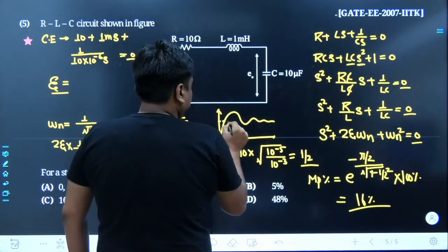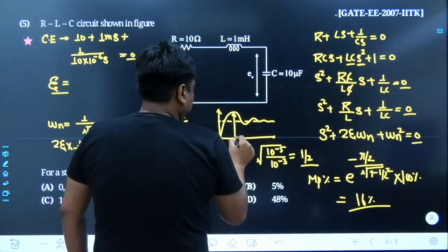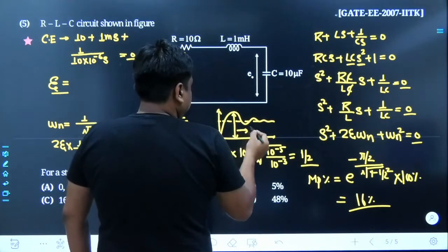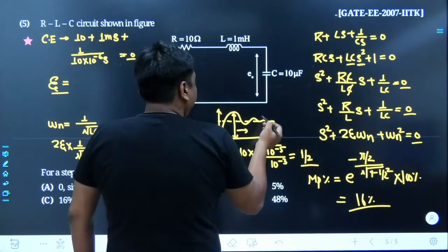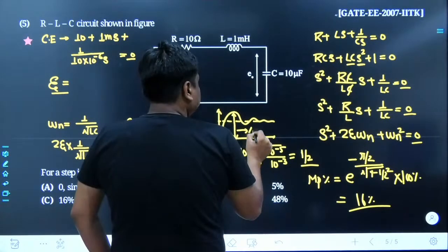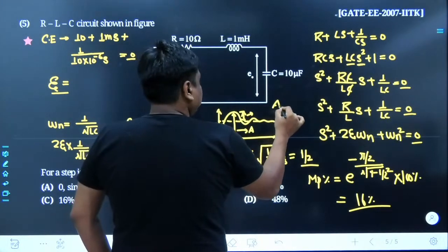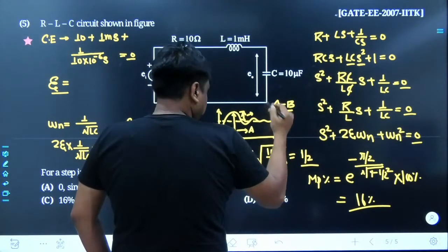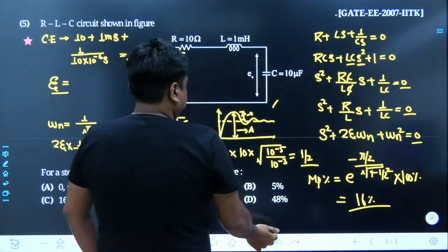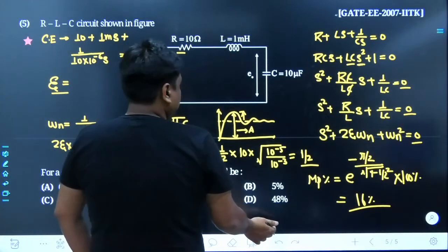And we had been focusing on the Mp percentage. How do we calculate the Mp percentage? Let's take this value as A, and this worth as B. So here we take A minus B divided by this. Agreed? Anyways, this has been the agenda.